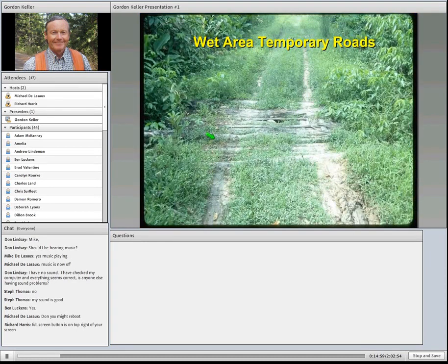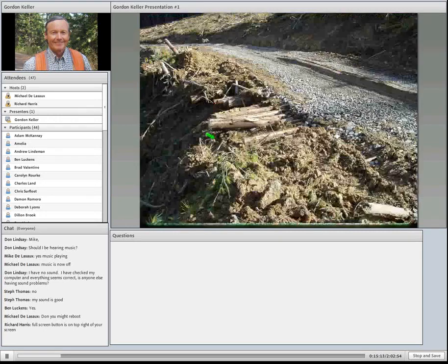This is kind of a time-honored approach, is to just put in something we call corduroy logs or simple logs. You can bridge over a wet area. There's one picture of one crossing. Here's a little drier site, but same concept. The logs are put in perpendicular to the road, usually with water flowing across the slope this way. And it's time-honored. The only thing is it's really appropriate for temporary roads, not for permanent road systems.